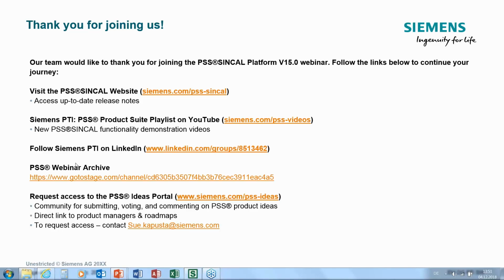All right, the next question is, does the fault location technique use any published fault location algorithms, or is it based on a search through the network trying to match the measurements to those produced by the fault application?